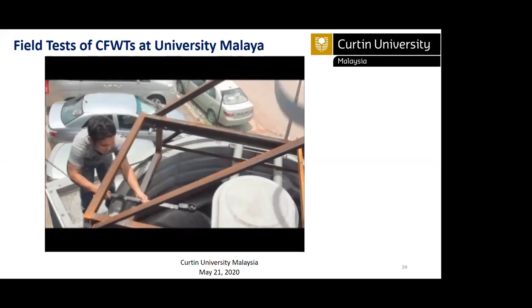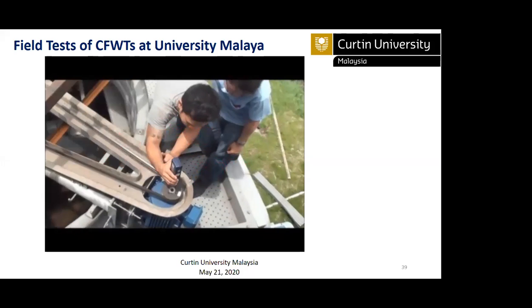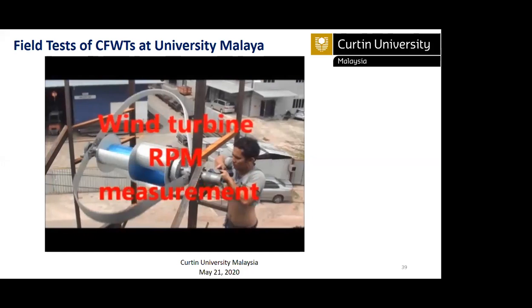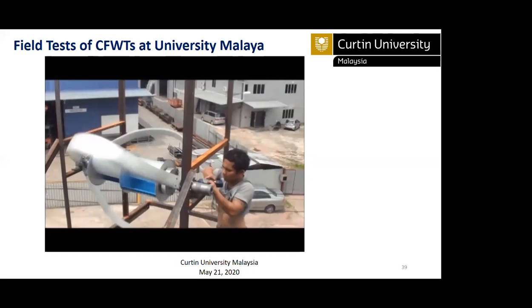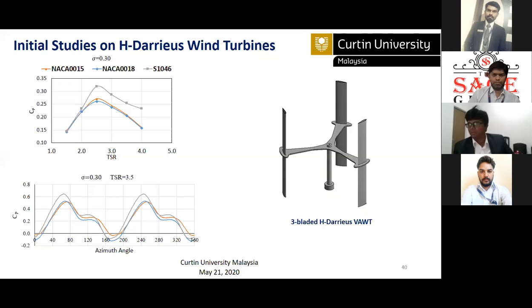We thought that was very low compared to the expected efficiency. So we submitted a government project based on this combined turbine, and we proposed that if we install a Darrieus turbine instead of a combined Savonius-Darrieus turbine, or use a counter-rotating Savonius turbine, maybe the power conversion can be much increased. Based on that, we submitted some projects for government funding, and luckily we obtained the funding for the ongoing research. We are now in Malaysia also, conducting some research on cooling tower exhaust systems.